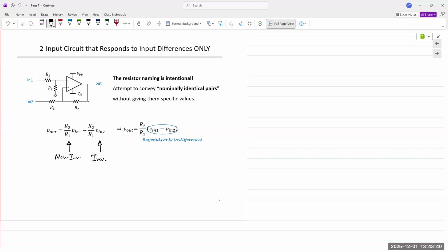Now, for the resistors, there is a longish derivation that we usually do for EE students in EE classes, but not so much in here. Once we go through the derivation, we make certain assumptions. One of the assumptions is the value of these resistors: the input resistors must have the same value, R1, and the other resistors must have the same value as the feedback resistor, R2.